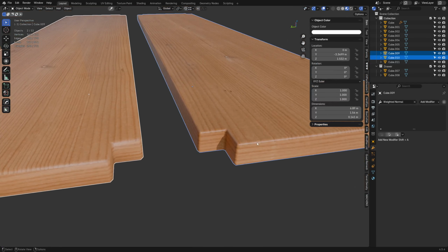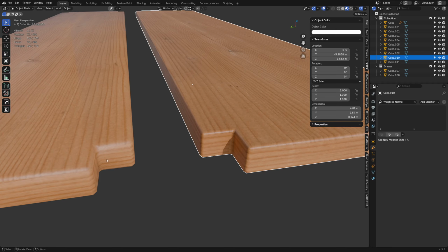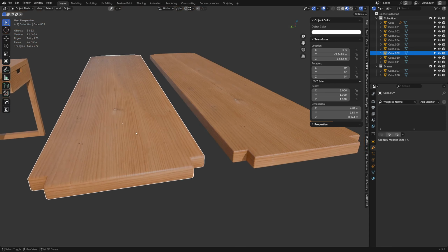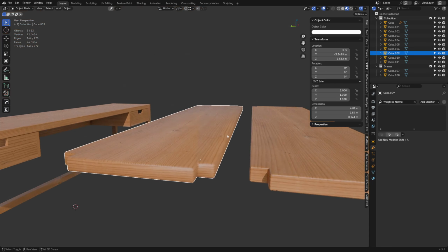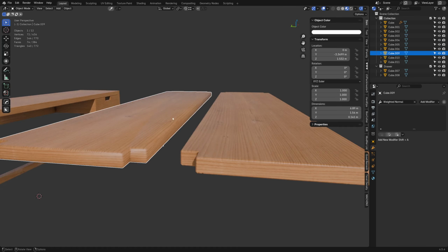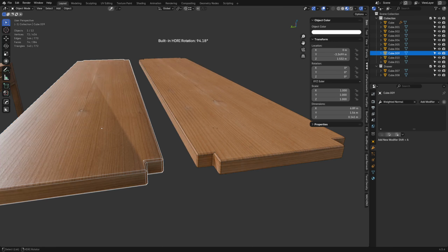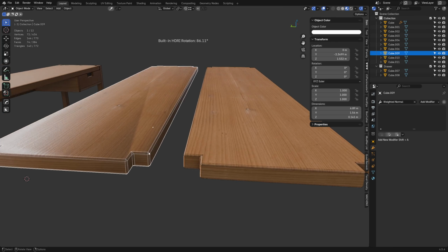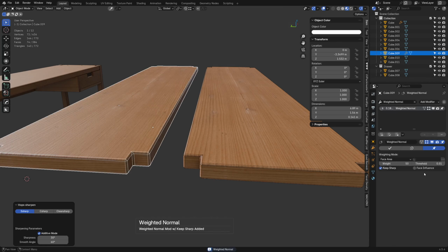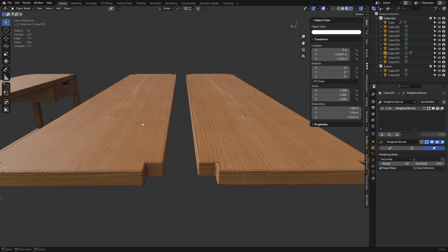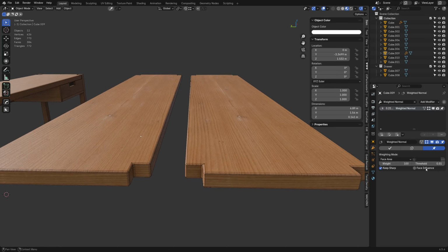You get different shading results out of these two. You can see this looks like a nice, clean, sharp bevel. This is a little bit softer and more squishy, perhaps. But the shading across the surface here doesn't look quite as good. Okay. So that's where a face influence of 100 is more useful because of these little weird artifacts like this. That's what you're looking for. I don't know if you can even see it, but there's a little tiny shading artifact in there, right? That's what happens with shade smooth when you weight the normal at 50. Sometimes that artifact or artifacts like that will still show up slightly. That's when the 100% there or strong face strengths is most useful.